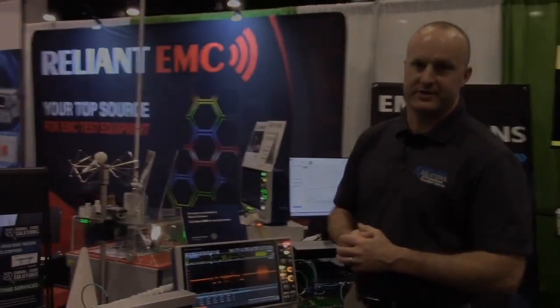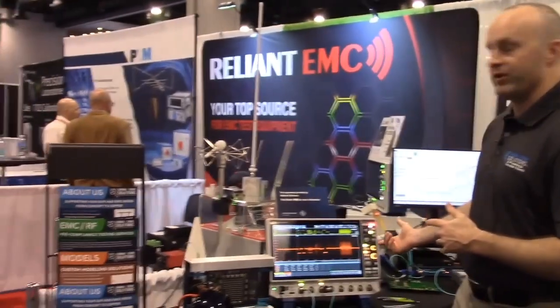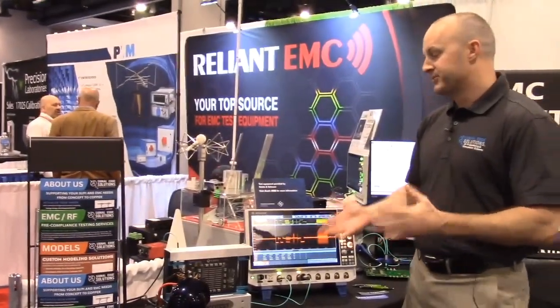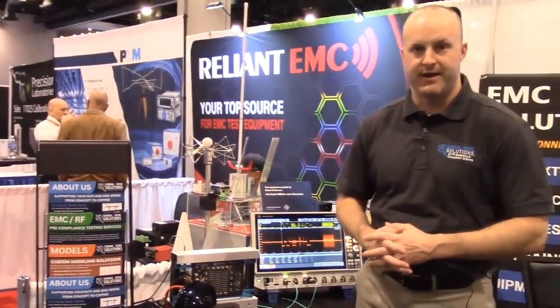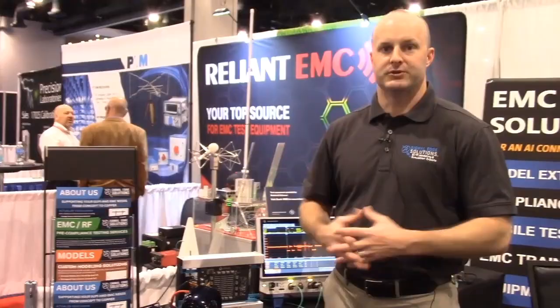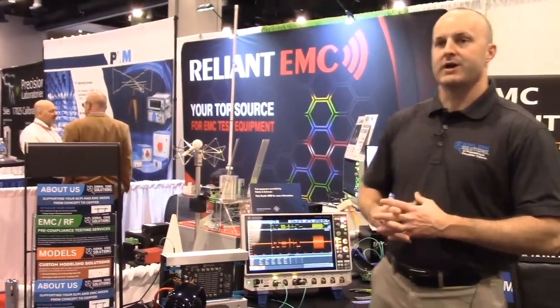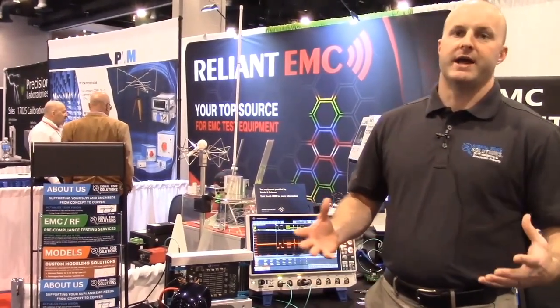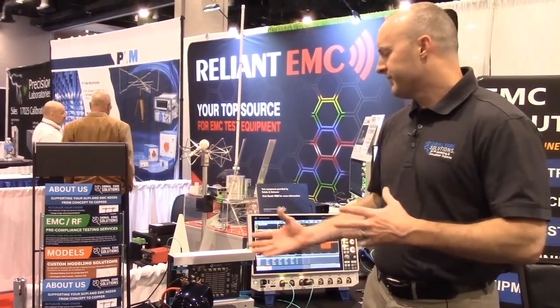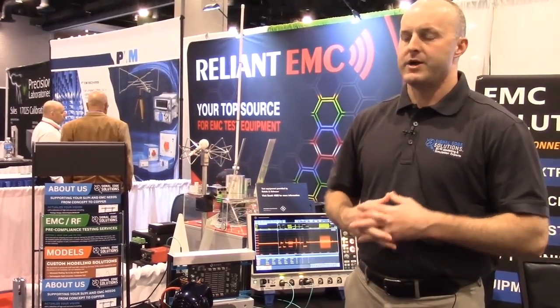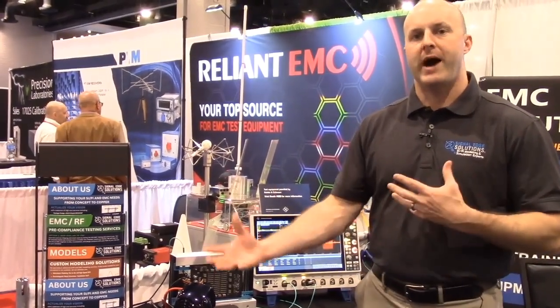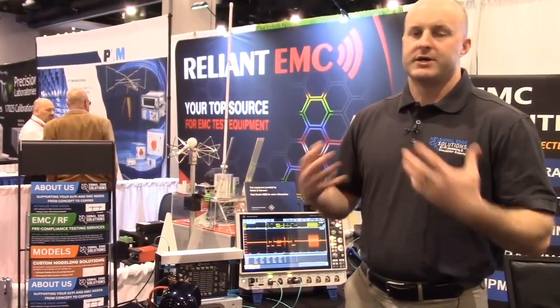The other demo I'm going to show you is with the S2000 here with PicoTest, and again with the Rohde & Schwarz MXO5. The S2000 is a 2000 amp transient step load solution. The benefit of these is emulating large high current ASICs for GPU and data centers. When you get a very large current board today and you're waiting on software, you can't validate or do all your power system testing until you have software.